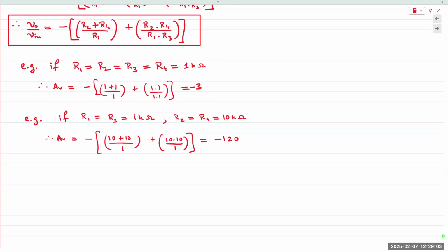A standard inverting amplifier, the gain is feedback resistor over the input resistor. So if you have a 3 kilo ohm resistor in the feedback loop, and a 1 kilo ohm resistor in the input loop on the input side, it's simply -3 over 1. Easy to do. Resistors are fine.